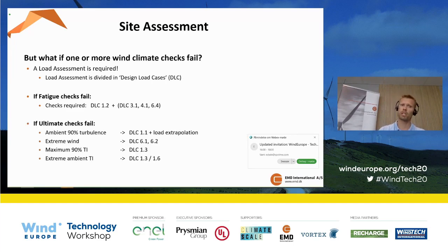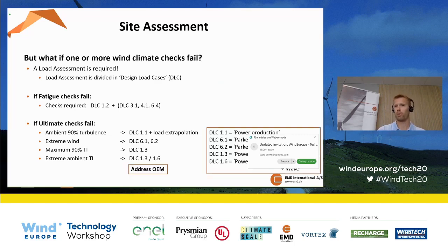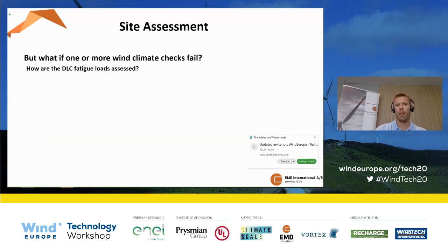So if the ultimate checks fail, it's more complex, and I line up here the design load cases which need to be checked, and also sort of what they include. And generally, this is quite specific to the particular turbine design, and it's generally advised to consult the manufacturer if there are significant incidences in these checks.